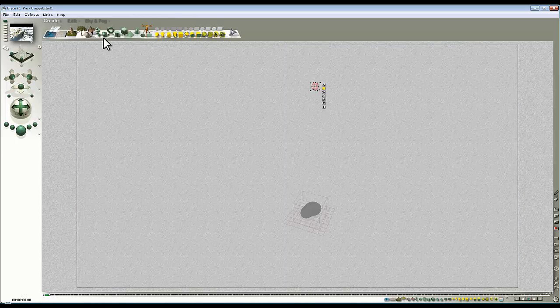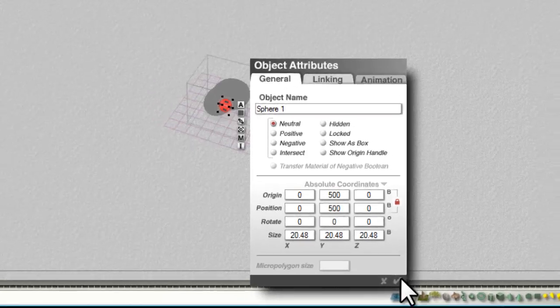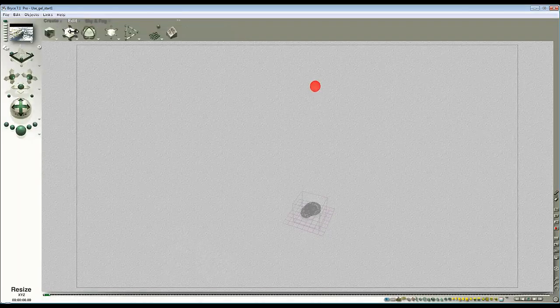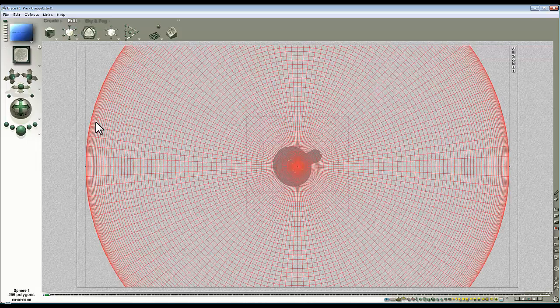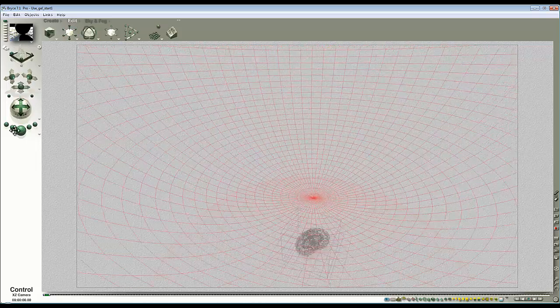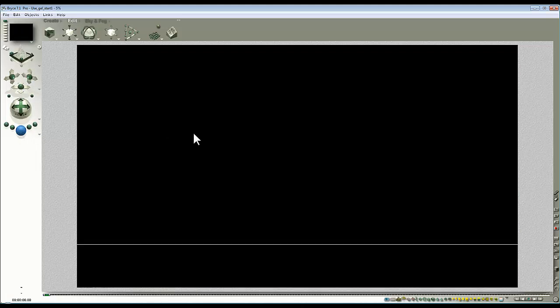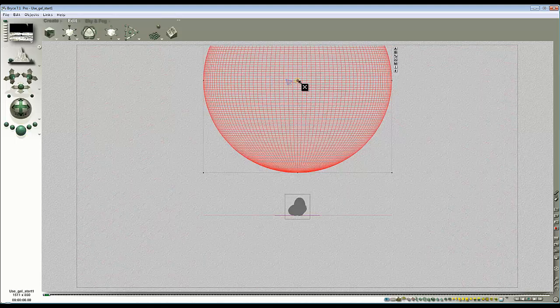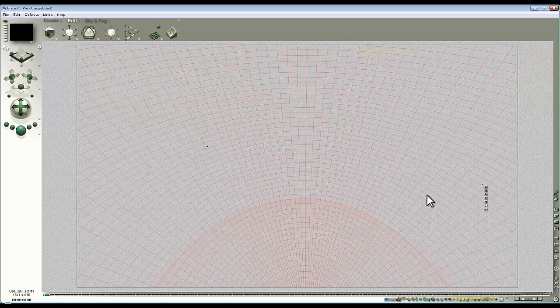So if I create a sphere here and then position it at the same origin as the light source, there we go, and then expand that sphere, not so much that we'll get clipping the ground, we'll come to that in a second, and then move inside this sphere, you can see now everything has gone dark. So even though the point of projection is inside the sphere, the light source is outside the sphere. To solve that is easy enough.